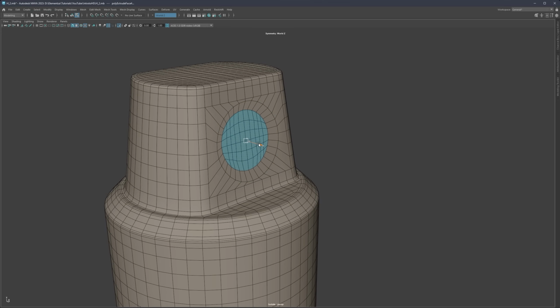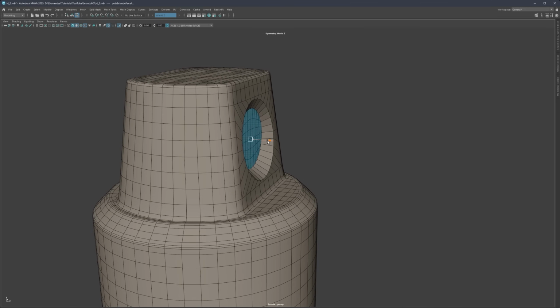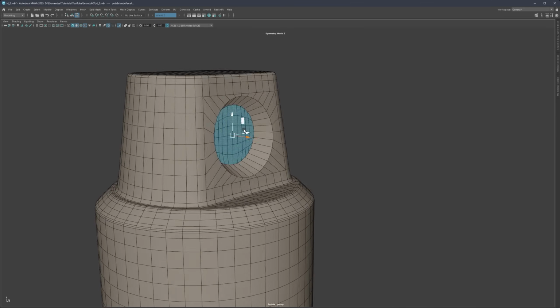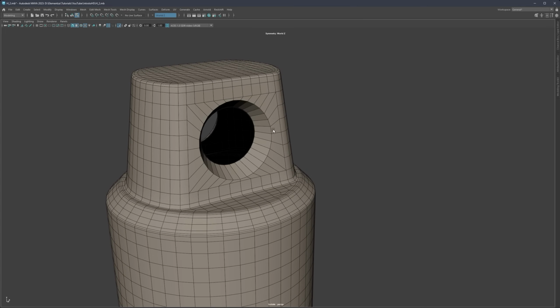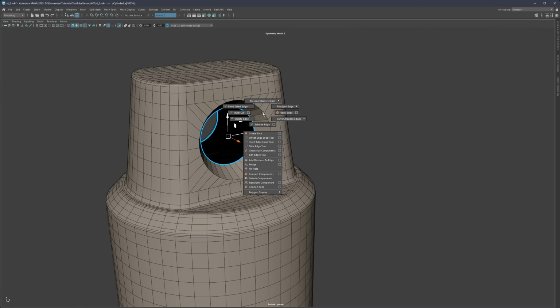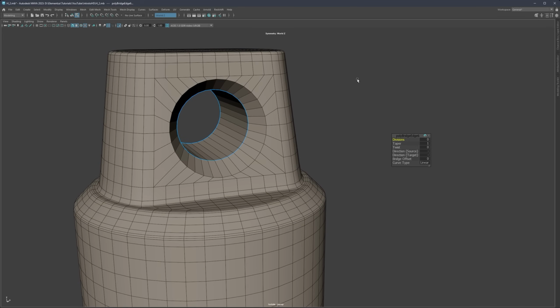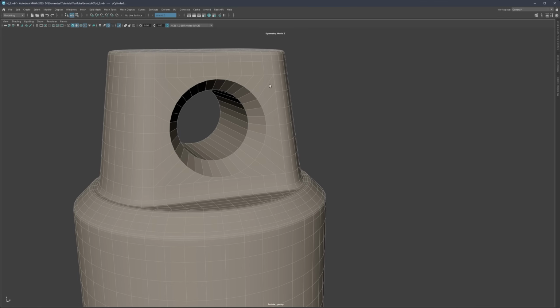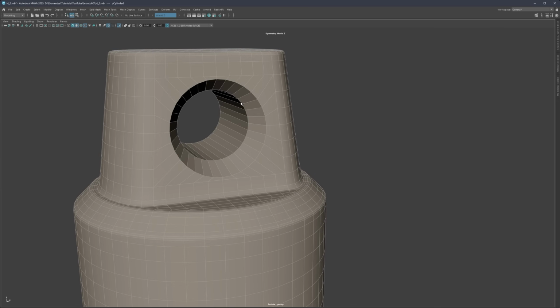I'm going to push it on the inside, and also scale on one axis, this one, because I would like to have more of a straight looking opening. Pushing it on the inside like so, and then we can simply delete. Now let's go to edge mode, double click here, and shift right click and bridge these two parts together like this. Hit Q to confirm, right click to object mode, and then simply 3 to preview and click away to get that smooth preview.